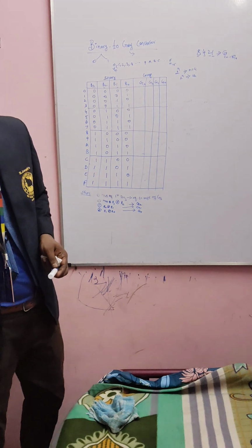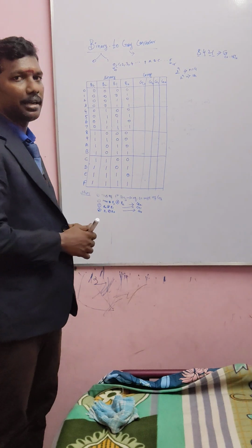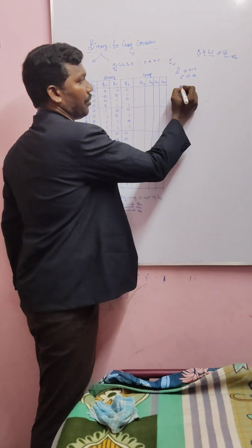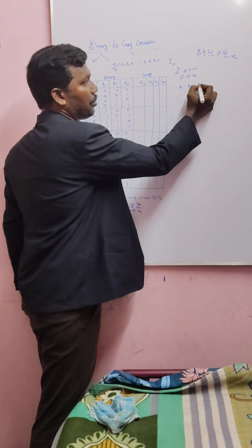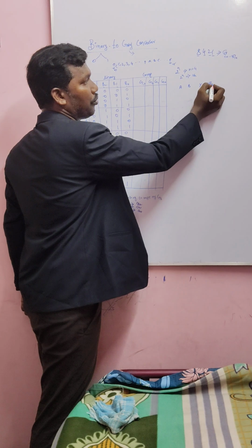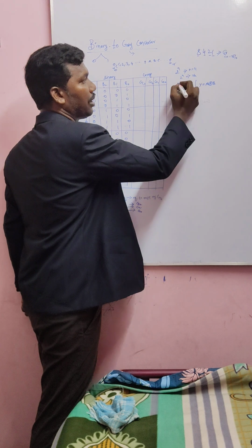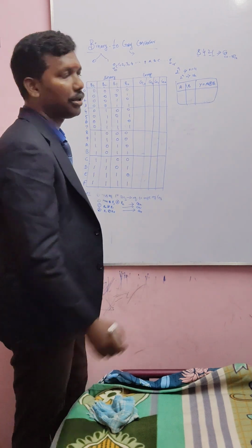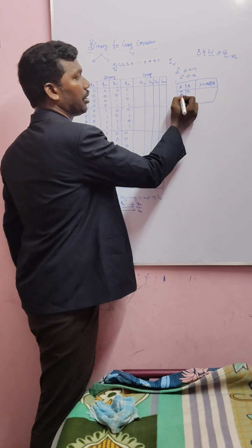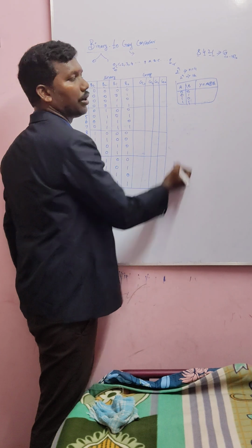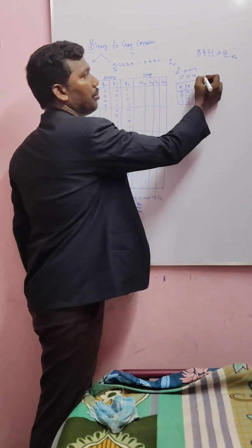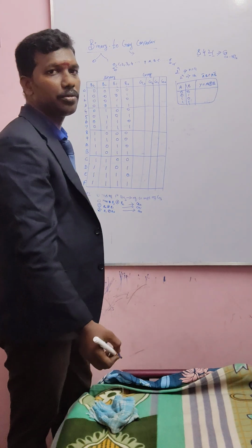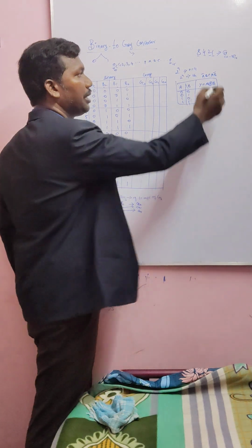So here what I'm trying to say is, before that, I keep telling you about the XOR gate, XOR gate, XOR gate. What is an XOR gate? I have A, B, 2 inputs, A exclusive-OR B. This is the truth table for exclusive-OR. Exclusive-OR and mod-2 addition will be the same. So if you have 2 inputs, there are 4 different combinations: 0 0, 0 1, 1 0, 1 1. What it actually means is that A exclusive-OR B is A bar B plus A B bar. That means one should be complemented, the other uncomplemented. The sum of both combinations is taken as XOR.